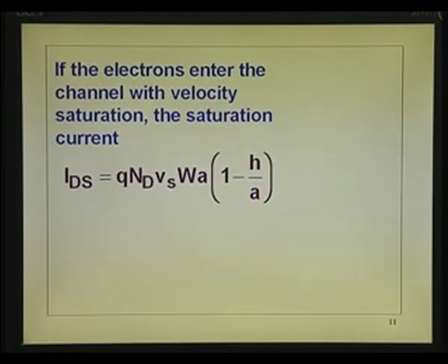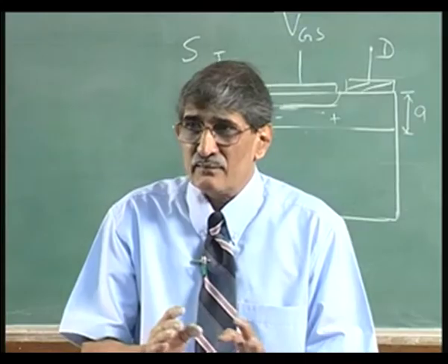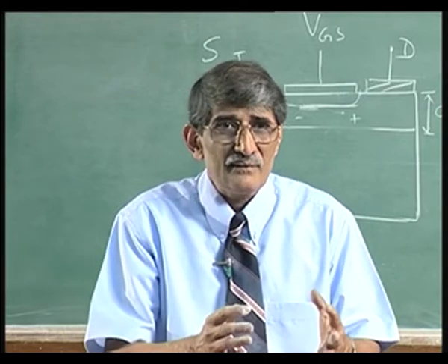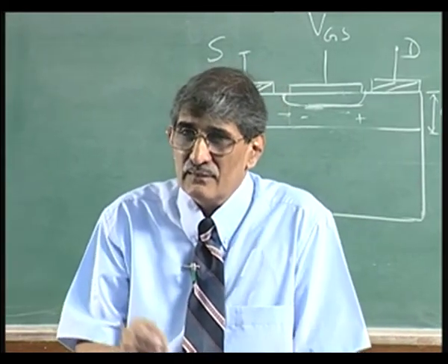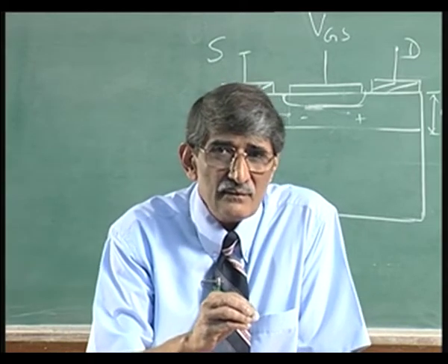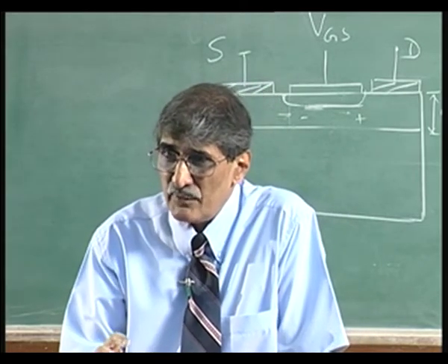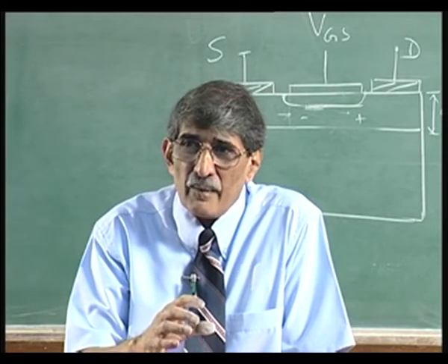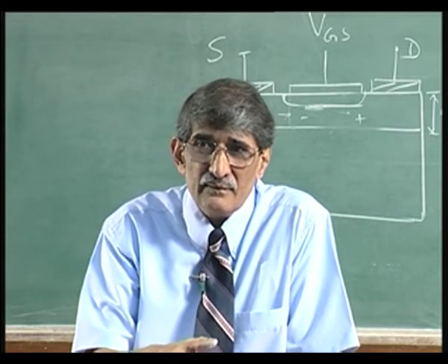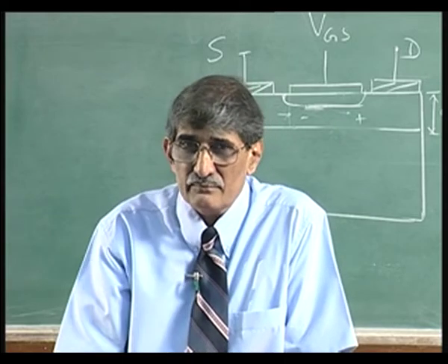So, few things now. I think we can just zip through this, because the concepts are over. Alpha Es L by Vp0, if it is very large, that is long channel devices, or pinch off voltage is small, such devices, velocity saturation takes place when pinch off takes place.